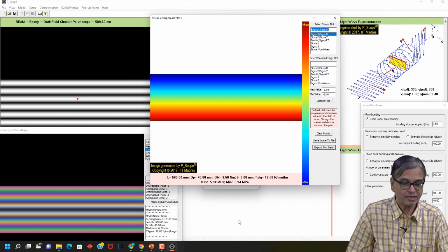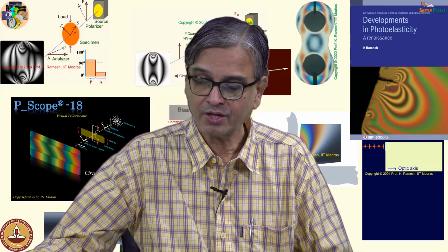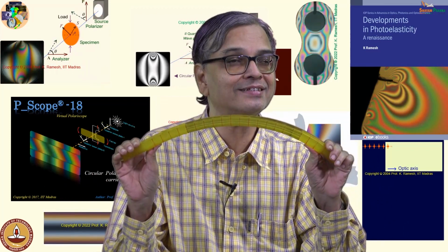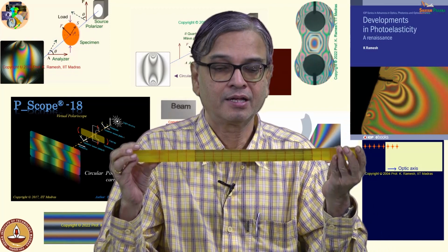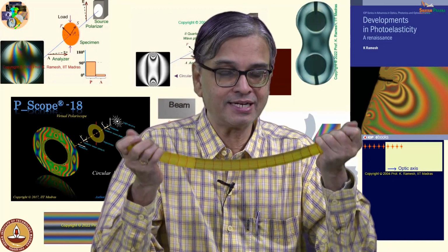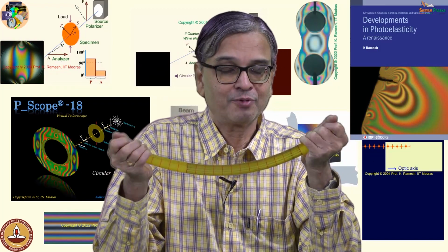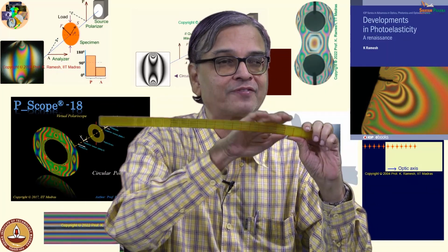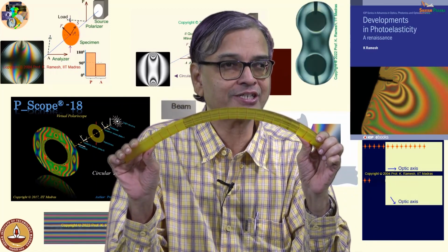And what we have done is, we have taken a beam where, when the bending moment is positive, it is bent like this, okay. Bending moment is positive means it is bent like this, okay. This is anti-clockwise positive, because in the class I have always shown it bent like this. When it is bent like this, the top surface is under tension and the bottom surface is under compression.